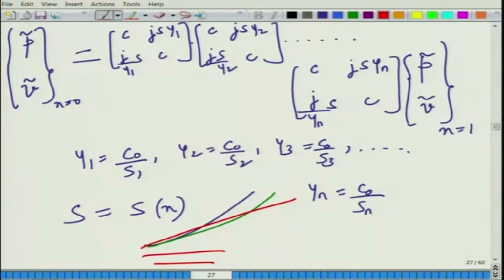Some simple area discontinuity, I mean basically cascading of area discontinuity matrices, and then multiplying it with a duct transfer matrix for uniform duct and generating the entire system of equations, deriving the overall transfer matrix or the overall 4 pole parameters for a gradually varying area duct of any profile. That can be easily done in a simple MATLAB code, and then we will do that just in a while.